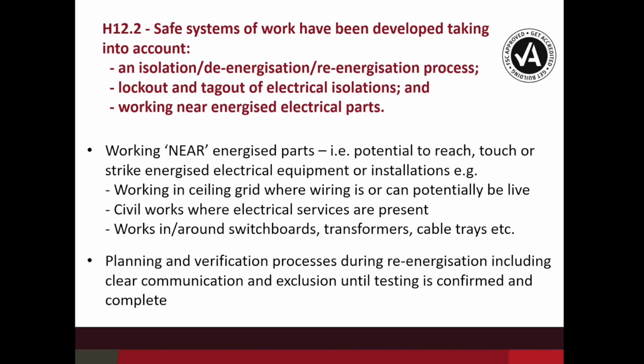We look to things like civil works where we know that certain conduits have live services in them. They might be installed by the actual construction project, but we understand what those are and how we work around them. And we're looking for defined controls in this space to make sure that when we're working in and around all these parts, including switchboards, transformers, cable trays, etc., where we have certain parts that might be live, we have an ability to set in place some control measures, which include things like isolation, physical barriers at times, sometimes labeling, color coding, and other various control measures, so that we can manage that working near the energized parts.